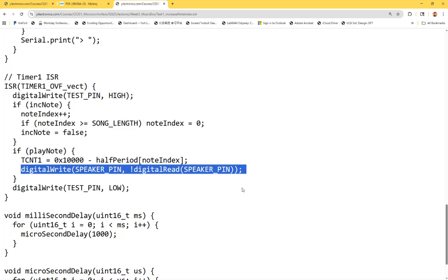I'm going to set up the timer here, start counting. However, I'm going to flip the pin, and then exit. It's done. ISR is done, right? The timer is still running behind the scenes. I got a new number set up there. Until when? Until another loop, until it finishes the counts being set up over here. Keep in mind, ISR is running here, and the timer is running here.